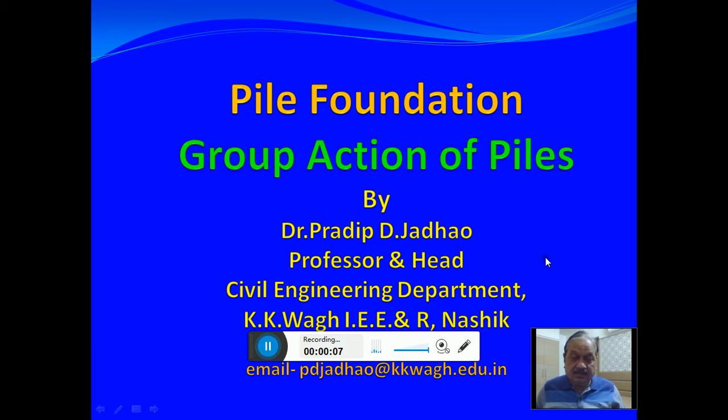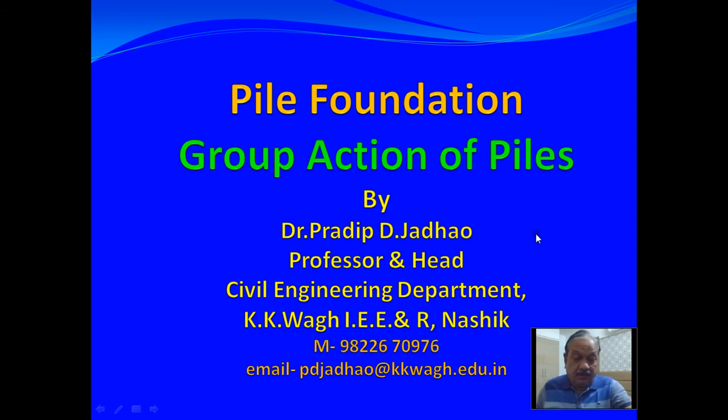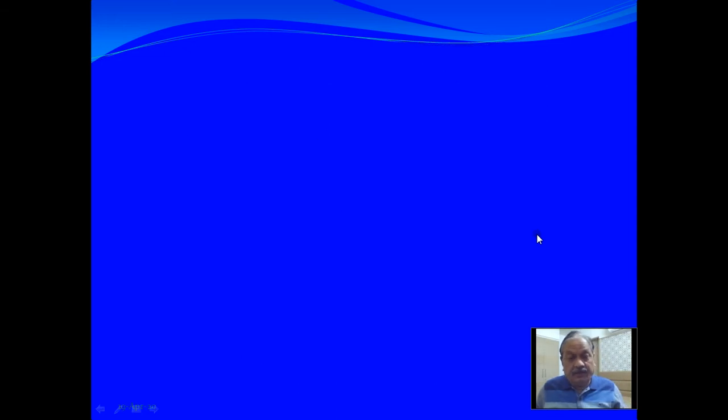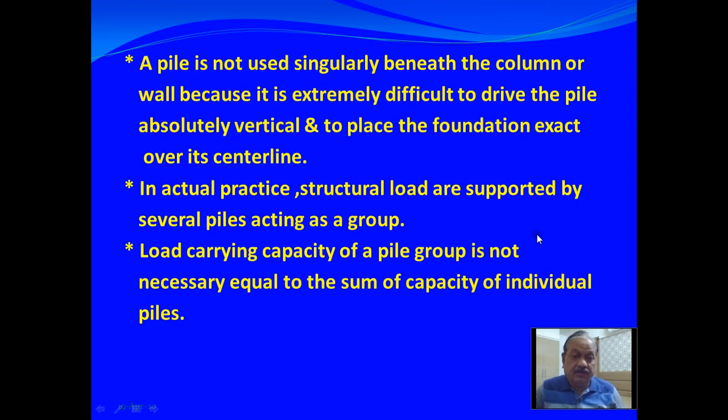In this session, we will discuss the group action of a pile. A pile is not used singly beneath the column or the wall because it is extremely difficult to drive the pile absolutely vertical and to place the foundation exactly over its center line. In actual practice, the structural loads are supported by several piles acting as a group.